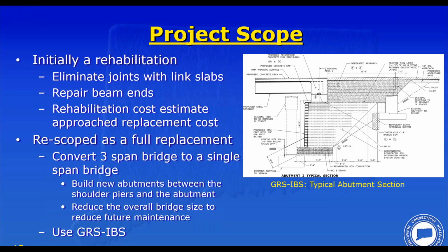And the concept is we're using layers of geosynthetic reinforced soil to support a spread footing. The bridge is integral with the spread footing. And then the backfill behind the end of the bridge is a reinforced approach slab, or approach, you should say. They call it integrated approach.